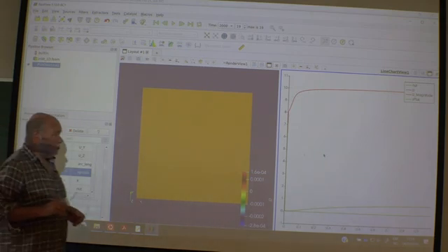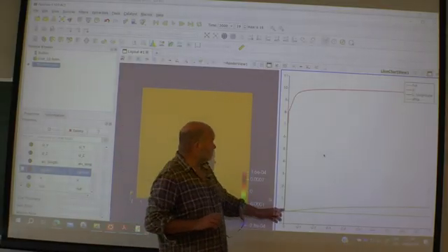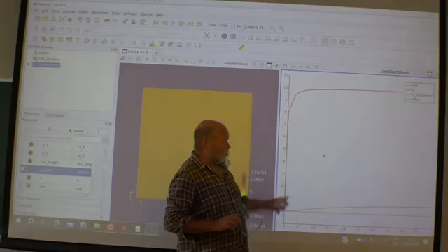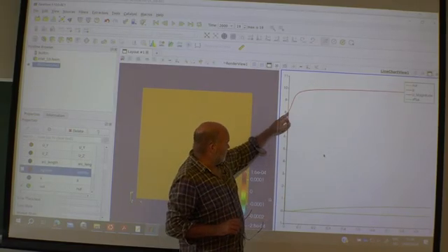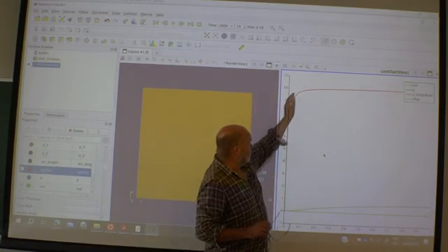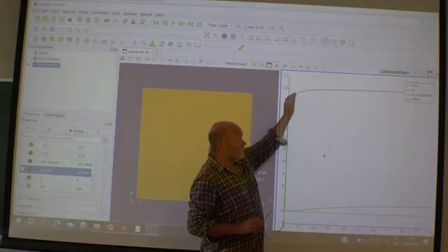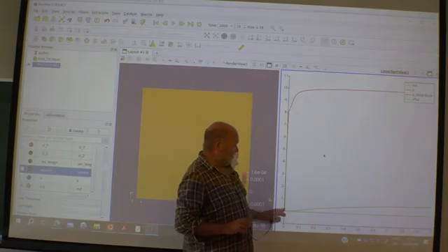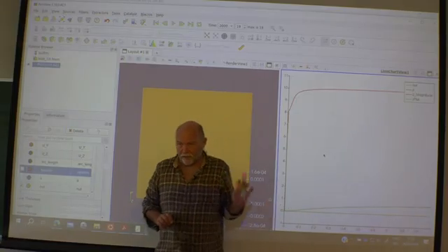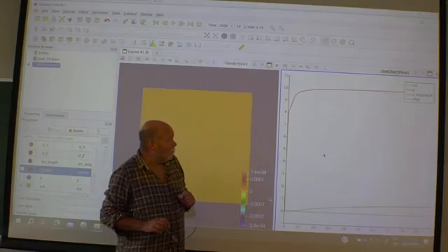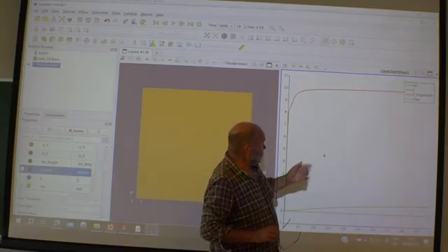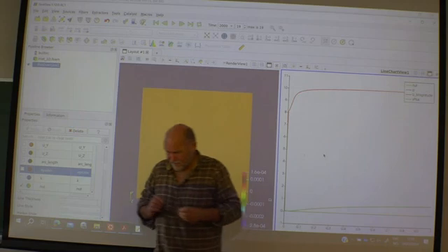Here you have the turbulent velocity profile. So it's very narrow here close to the wall. This one doesn't look too good, does it? And then he sort of levels off. This turbulent profile I can accept, but not this wall treatment. So I still haven't resolved the wall good enough here. But we are on the way at least. The pressure doesn't really matter.